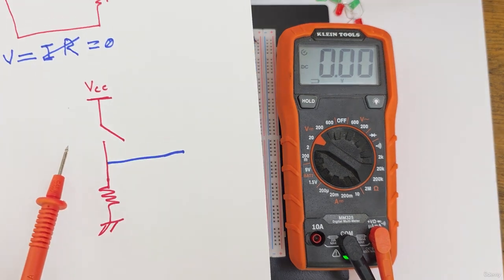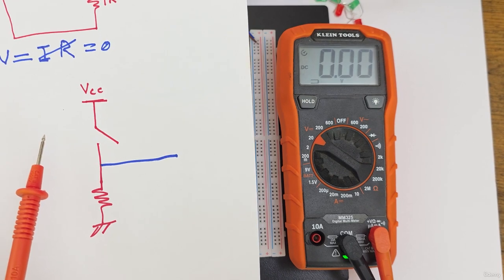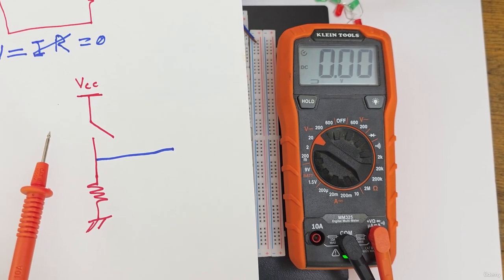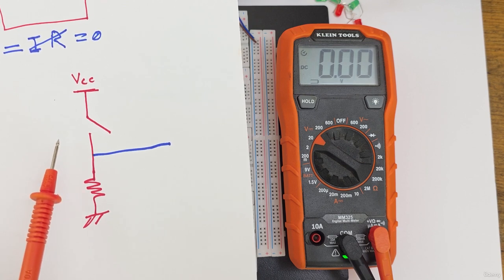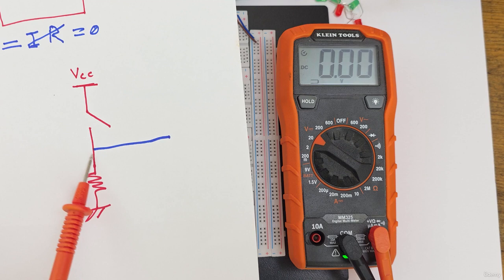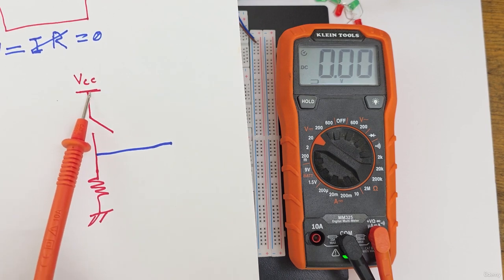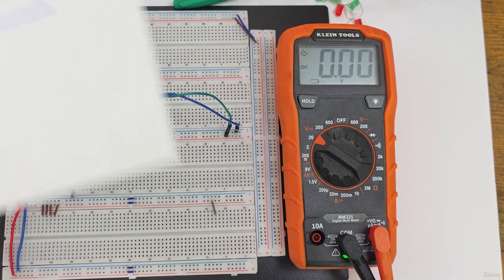By the way, I know that I am explaining in details, but I know that most people are not aware of the hardware, and that's why I am explaining every step. So we need this to connect, to measure the output from this pin, not from this pin, because if you put your multimeter here, you will measure the VCC.